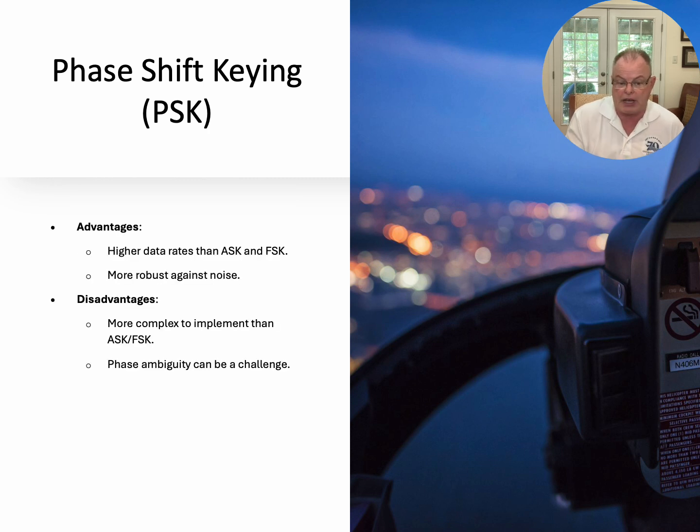Its advantages: it's a higher data rate than either ASK or FSK. It's more robust against noise. The problems come in that it's more difficult to implement. It requires more circuitry and more decoding. And at times you can get into phase relationship issues that make it a little bit hard to sort out some things.